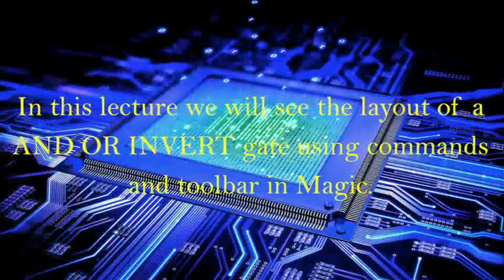In this lecture, we will see the layout of an AND-OR-invert gate, that is AOI21, which is drawn from the twisted schematic. So at first, open the terminal window by pressing Ctrl, Alt and T. Then type magic, press enter.